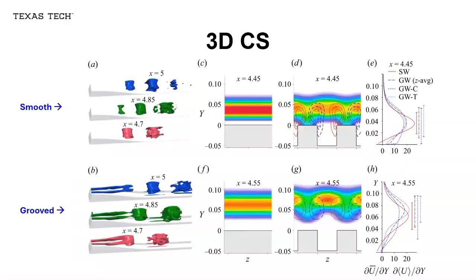Okay? So now we did the phase-locked ensemble average. Here we're showing the 3D view of this phase-locked ensemble average. Here again, this is lambda 2. And what is happening is that because of the grooves, there are two additional structures, actually a series of counter-rotating vortices that start at the corners of the groove and connect with the spanwise rollers. And these streamwise vortices being induced by the grooves are basically inducing a wavy shear layer, or in other words, inducing a waviness in the spanwise roller.